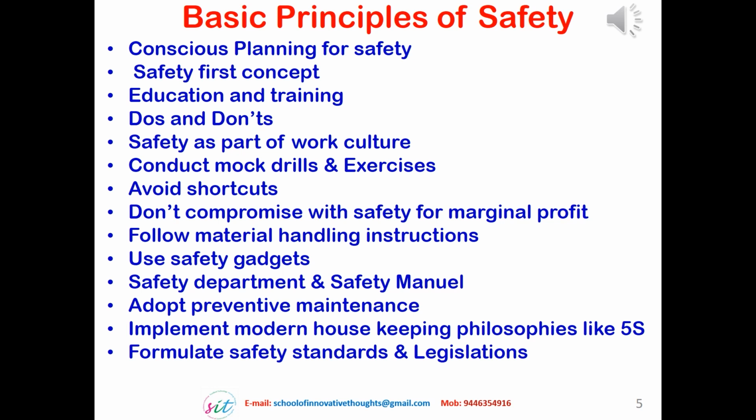Next point is, follow material handling instructions. Each material has to be handled in the way it should be handled. Many a time there is a guideline or a checklist how to handle the materials. Then we have to give proper safety gadgets to the workers, like safety belt for the people who are working at a height, gloves for the persons who are handling hot materials or abrasive materials, gumboots for the people who are working with concrete or materials like that, then goggles for the people who are doing the welding or such works, then masks for protecting our lungs when we are working with dusty materials like cement.